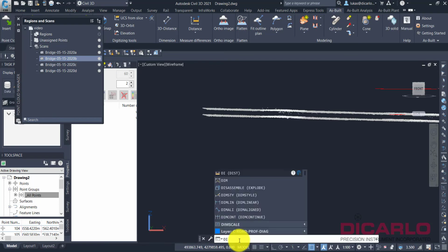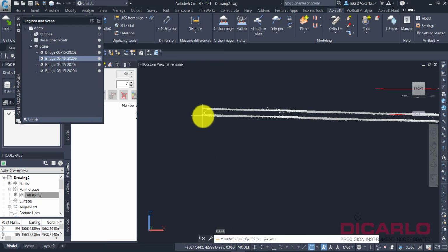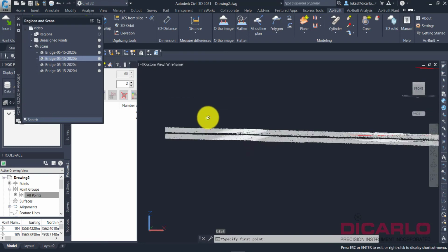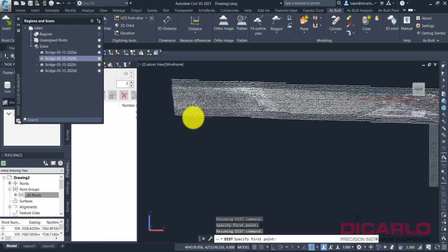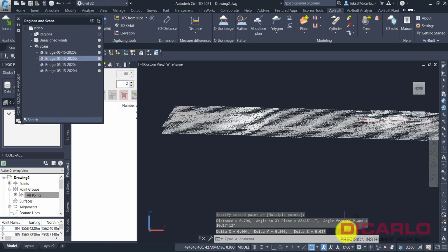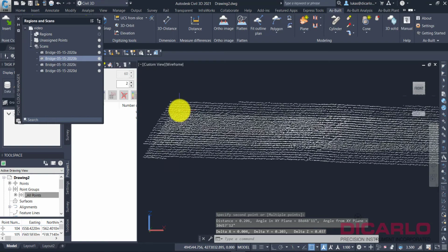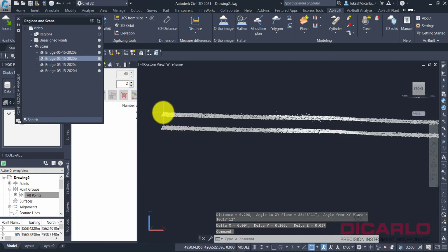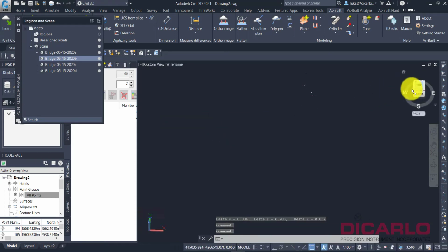So that's the one thing that I didn't notice originally. And what we'll do is click, and then we'll just do a vertical distance. See, there's a vertical distance of what, 39 millimeters. So not horrible, but that's the distance between these two. And mind you, the reason it's snapping this stupidly is because the coordinates are UTMs, and CAD really doesn't like it.